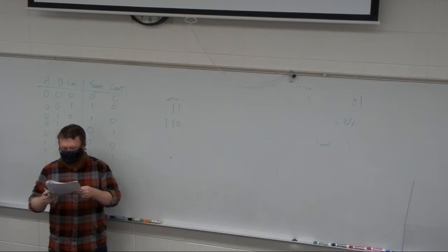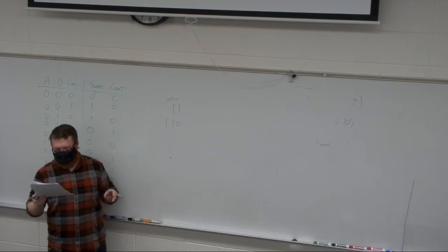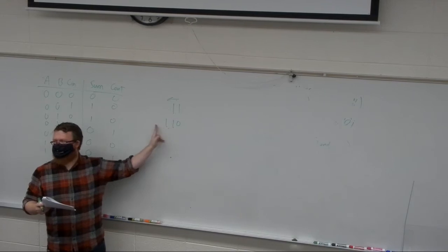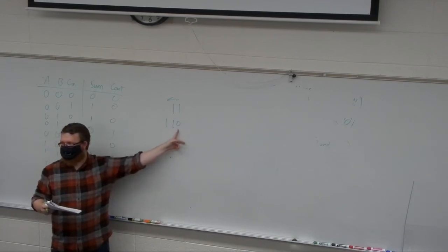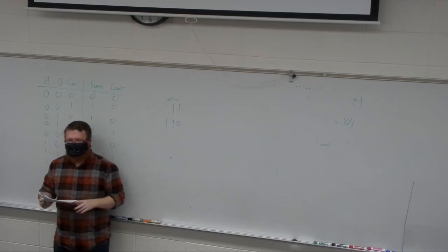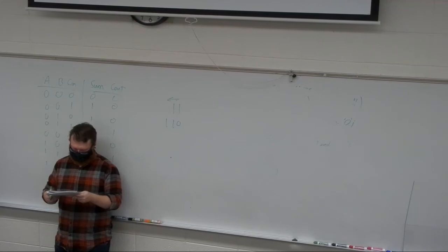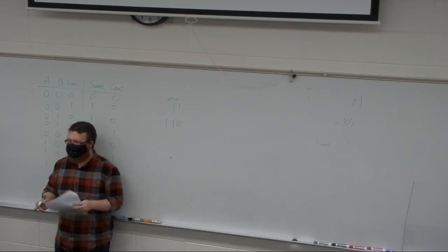Yeah. They mentioned one called end around barrel shifters, which we don't do much with. End around is if I had this one and I shifted it left, this one pops out this side and comes back in the other side. Those are really good for like pattern generators. Mostly we're going to focus though on this one, the zero backfill.